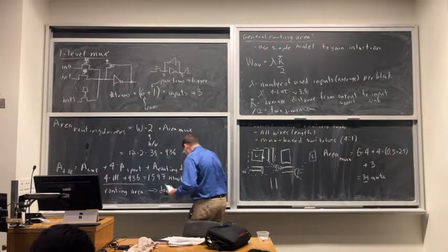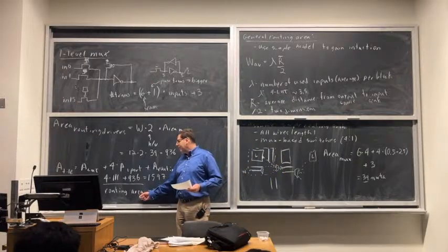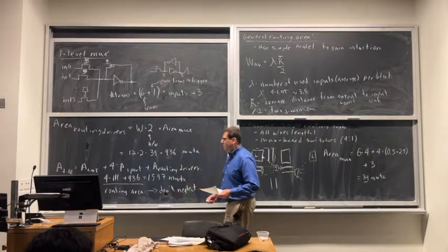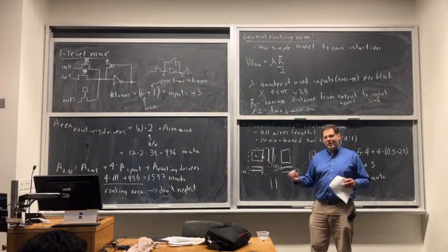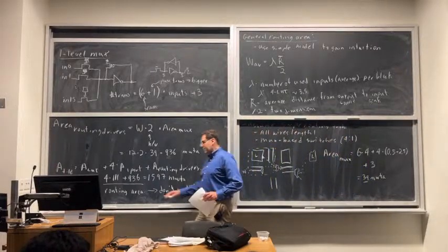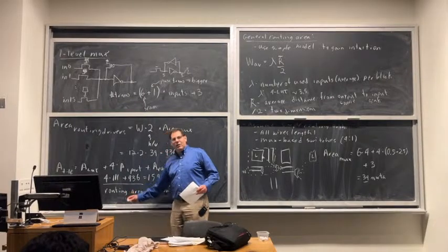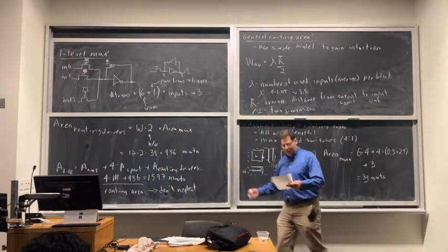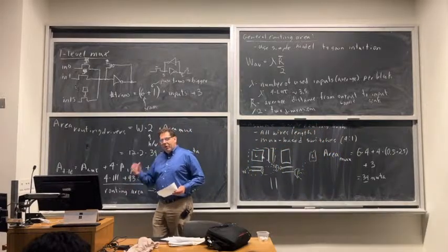So when we're doing FPGA architecture studies, we always have to be thinking about the routing area. And it is a mistake that many people have made, because it's easier to think about the logic blocks and other function blocks, so they don't really want to think about this as much, because it's harder to estimate channel widths and so on. But it's not a second order effect. It's actually the first order effect. So you have to consider it. Now we did a pretty simple architecture here.